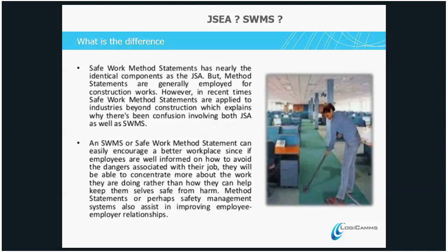The usage of the term SWMS has increasingly been applied outside of high-risk construction work. And this is where some confusion has arisen as to whether we should use a JSEA or SWMS. When a task or a job is identified as high risk, we must use a SWMS.